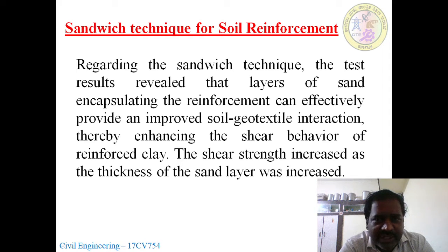Regarding the sandwich technique, the test results revealed that layers of sand encapsulating the reinforcement can effectively provide an improved soil-geotextile interaction. We have already studied that sand is very important here, thereby enhancing the shear behavior of reinforced clay. The shear strength increased as the thickness of the sand layer was increased. So obviously that depends on the sand thickness in the layer. So it will be very effective in terms of shear strength.